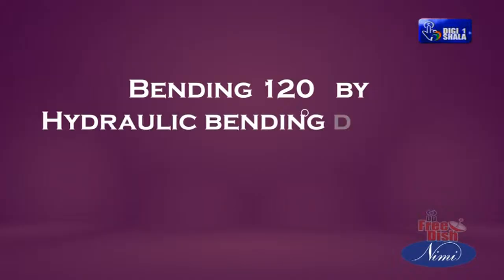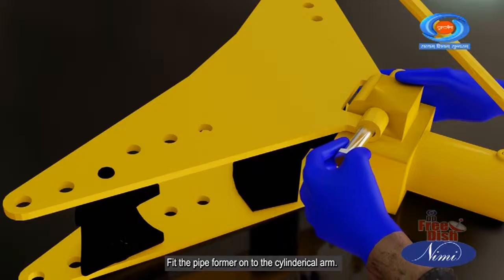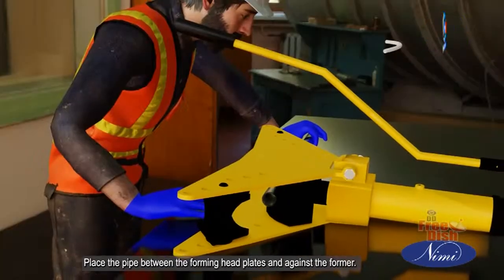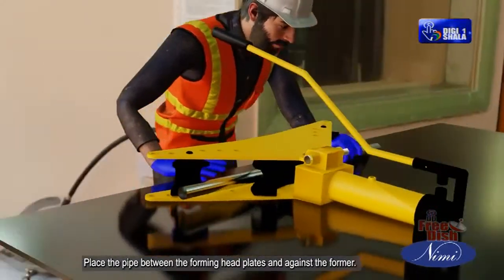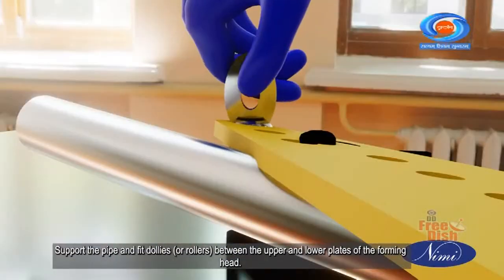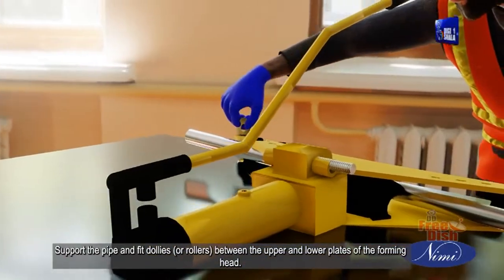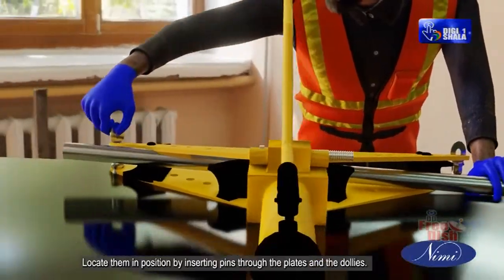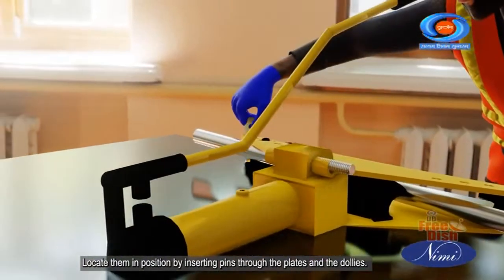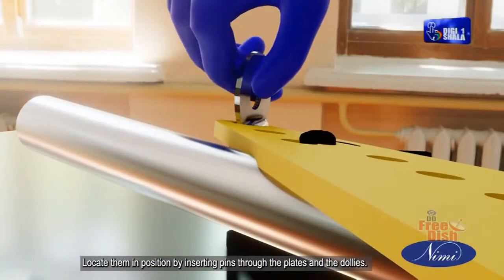Bending 120 degree by hydraulic bending machine. Fit the pipe former onto the cylindrical arm. Place the pipe between the forming head plates and against the former. Support the pipe and fit dollies or rollers between the upper and lower plates of the forming head. Locate them in position by inserting pins through the plates and the dollies.